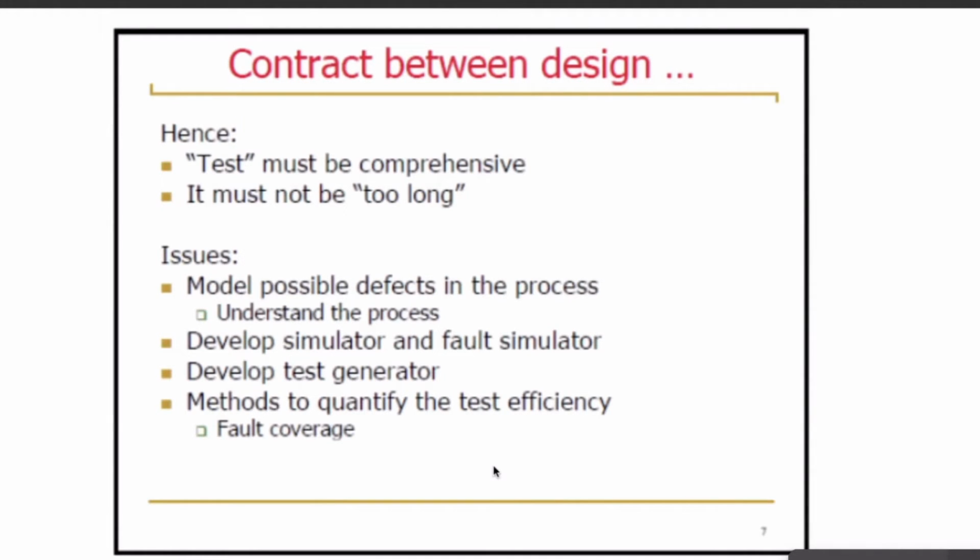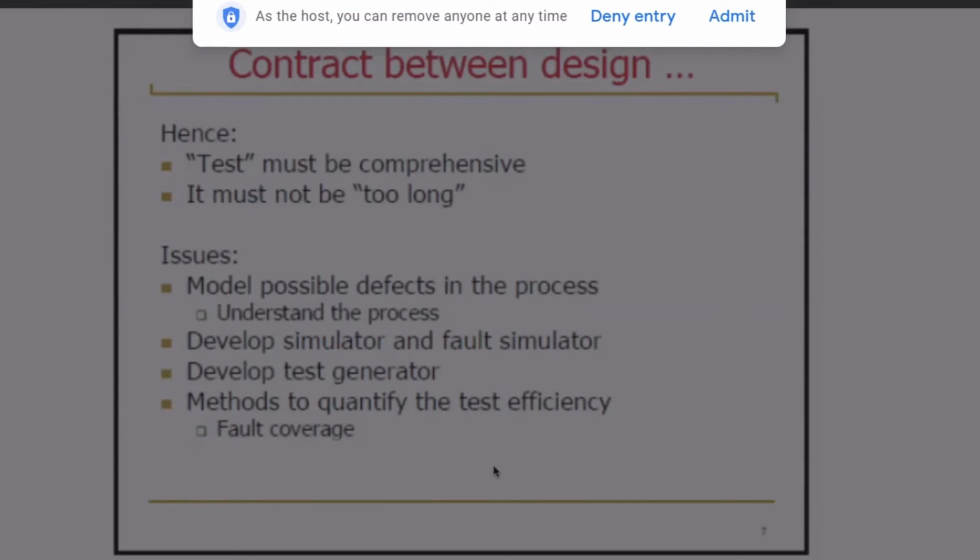First, you select a fault model, like the stuck-at fault model. There is this number of circuit lines, total input, output and intermediate lines, and every line can be stuck either at one or at zero.